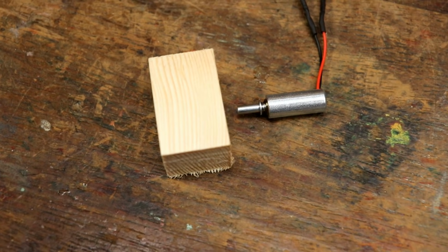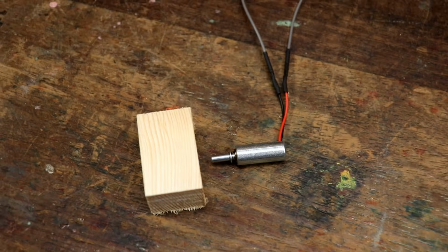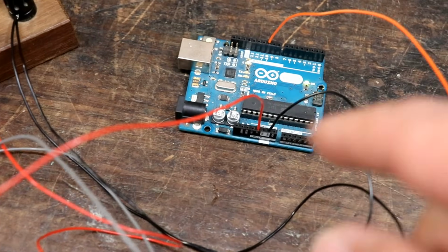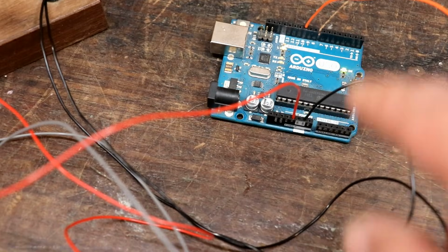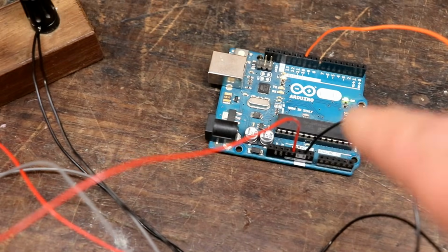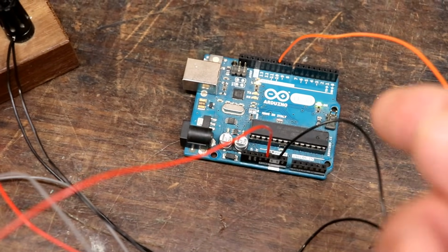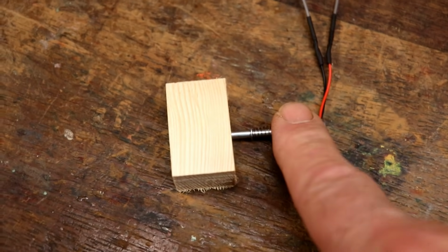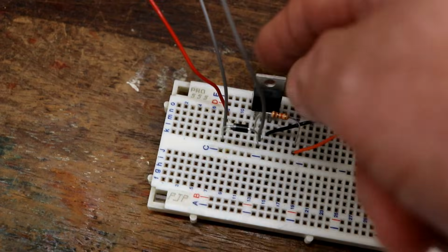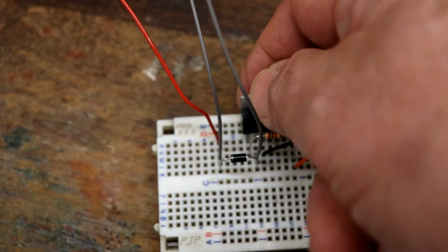And there we have it. I'm actually running it off the first, most basic example sketch that you get with the Arduino Integrated Development Environment, IDE, I can't bear acronyms, that blinks. It just switches an output on for a second, then off for a second, and it's doing that. So that's lovely. So that's drawing over half an amp. And the Darlington pair here is doing all the switching.